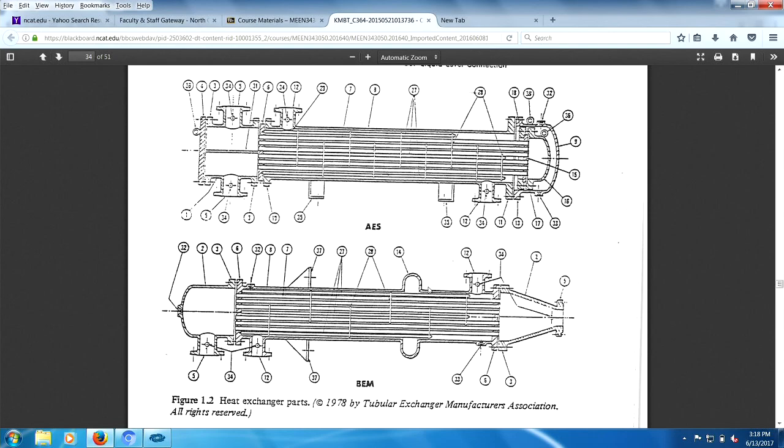The fourth hold point might be to watch how they handle this expansion joint. This expansion joint, you want to be there when they pressure test the bellows. Should recognize what we're talking about has implications through all kinds of equipment, right?